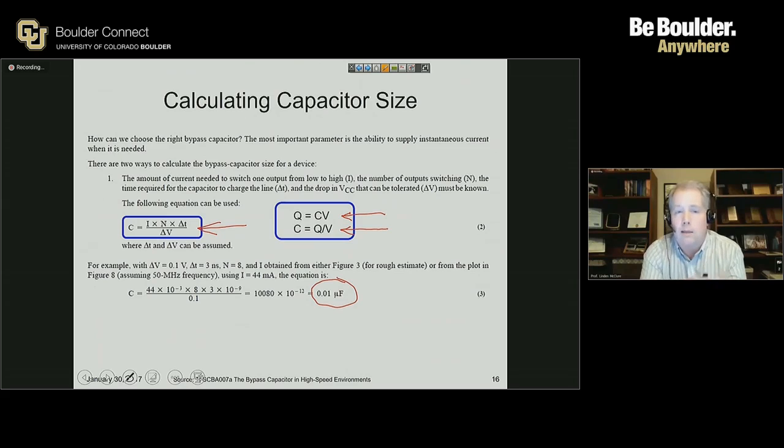And there are at least a couple of different ways that people approach this. One is that they start with all those capacitors populated in their board, and then they test it and keep removing capacitors until they get to a point where the system starts to fail or is at a marginal level. Another way people do it is they start with no capacitors on the board, and then they start adding capacitors until they get to the point where it passes. And each of these approaches is done at least in part to try to optimize design cost.